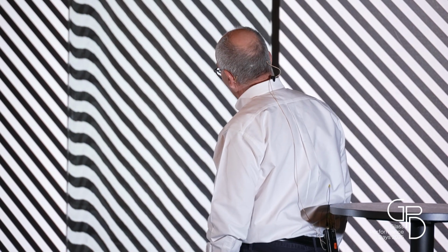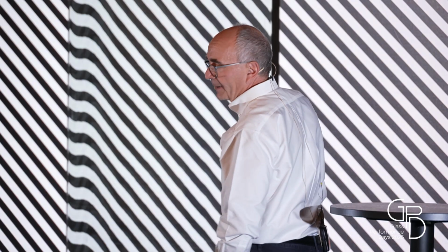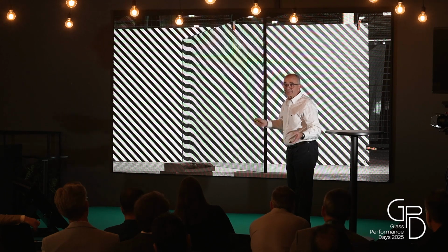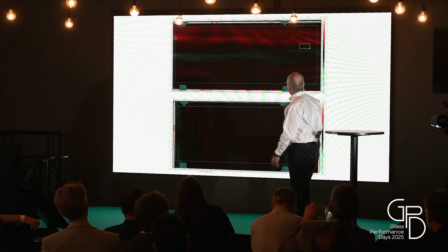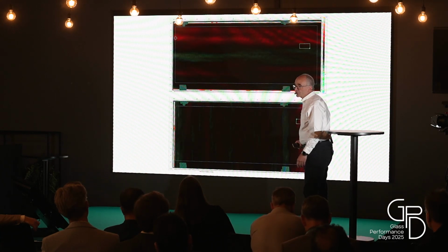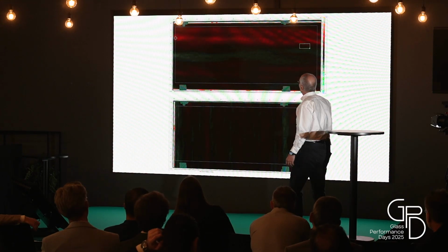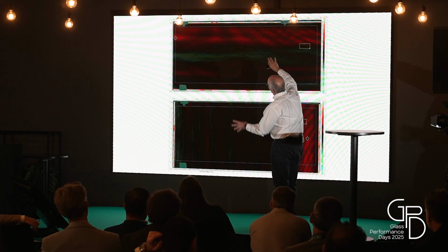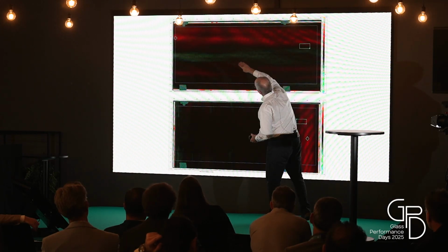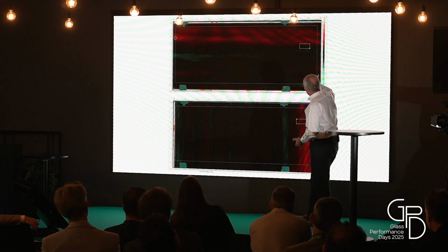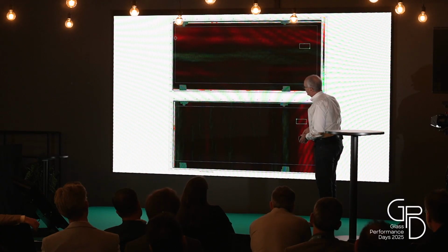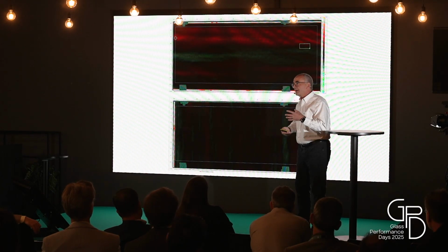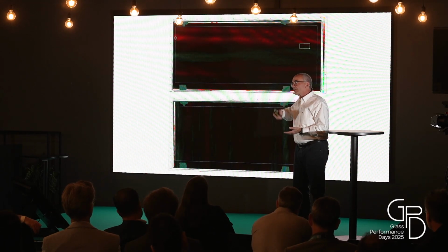What we did after that is we took the same glass and sent it to Montreal to be scanned on an automotive system, the same one where you saw the robot. And that's the distortion that Synerjet came up with. You have a long, very shallow distortion on the top, and this band on the right. In automotive, they analyze the vertical and horizontal separately.